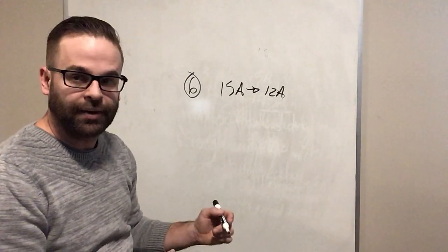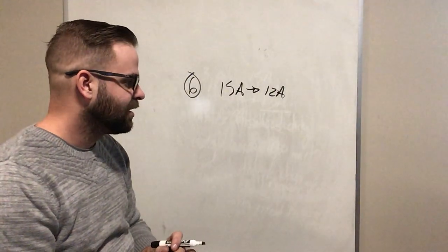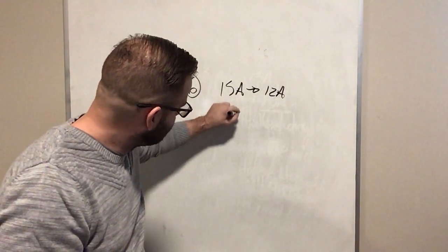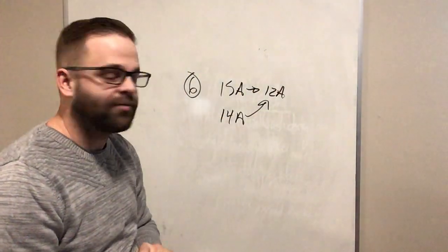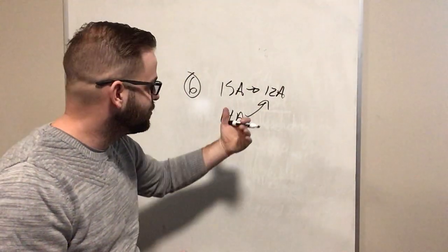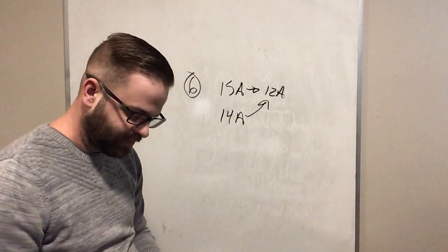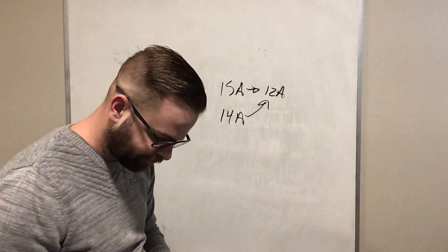So what you end up seeing every day is if I calculate out my load and my load is 14 amps, well 14 amps is greater than 12 amps. So I need to go to the next larger size breaker in that case. So my calculated load cannot exceed 80%.